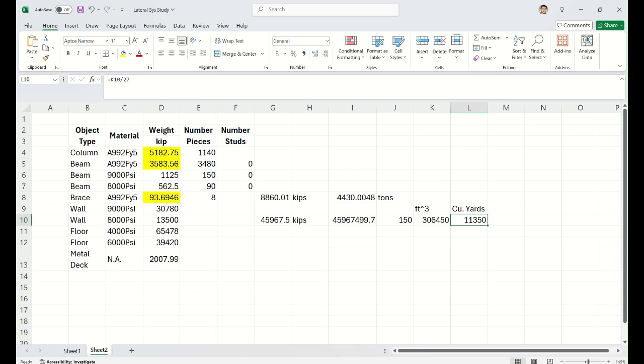Typically, software like ETABS and Revit, if you model correctly, gives us a more precise steel or material takeoff. In the old days, my generation, there was no 3D model. They used structural drawings, looked at them, measured them, and calculated beam weight, length, and number of beams, and came up with an estimation of steel tonnage for each group, right?